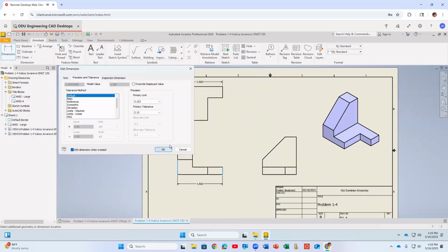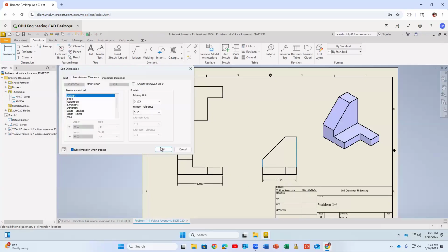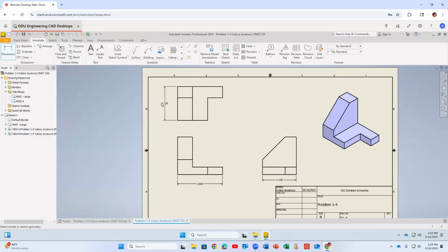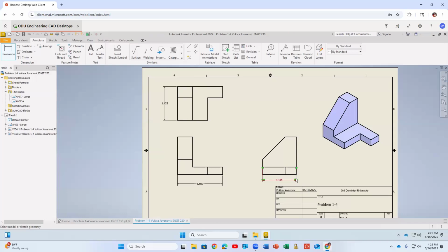That's the same dimension. So this is called over constraining. When you have it in two different places is not good. It's just because I have more space in the lower one, I'll keep it there and I'll remove the one I have on the higher one. So then we have another maximum dimension, which you can put in this projection, and the same one will be here. That's how they're connected, okay? And I just need one. Again, I have more space here. That's why I will leave it there and I will delete this one. No other reason, really. It really doesn't matter where it is.